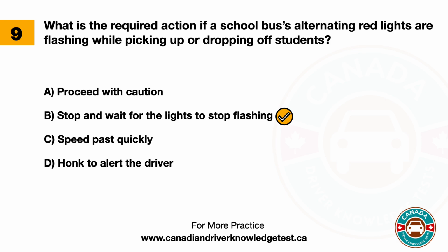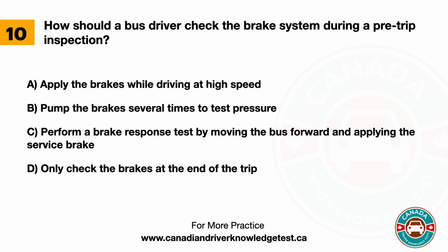Question 10. How should a bus driver check the brake system during a pre-trip inspection? A. Apply the brakes while driving at high speed. B. Pump the brakes several times to test pressure. C. Perform a brake response test by moving the bus forward and applying the service brake. D. Only check the brakes at the end of the trip. The answer is C. Perform a brake response test by moving the bus forward and applying the service brake.